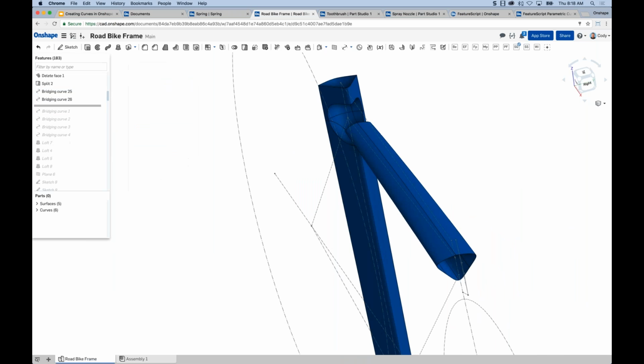All right, so quick question. Can bridging curves be used with other modeling functions besides loft? Yes, absolutely. Fill would be the other common one. I would say they're both equally common. I could see other scenarios where it could be used, but I think 90% of the time it's probably going to be lofts or fill, just because of the nature of it, because it's intended to bridge two things and fill that gap, and there's not a ton of other commands you would use in that scenario. But I could be wrong.